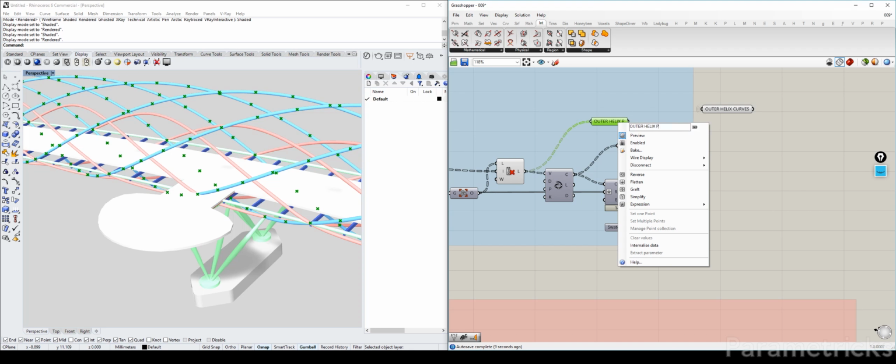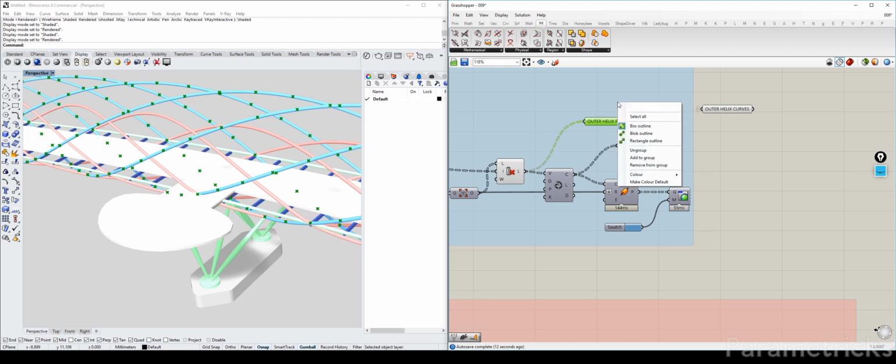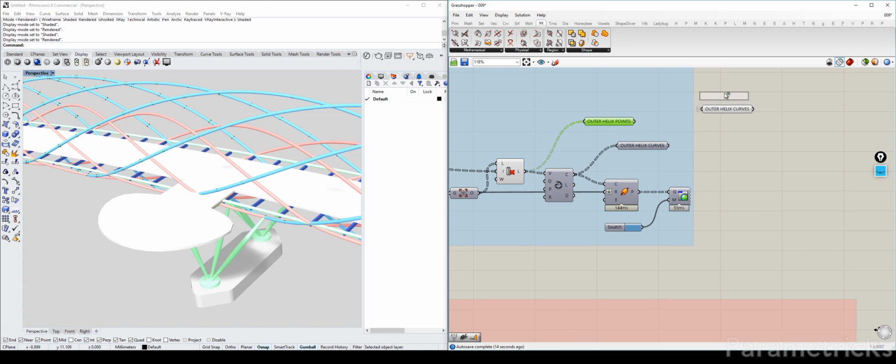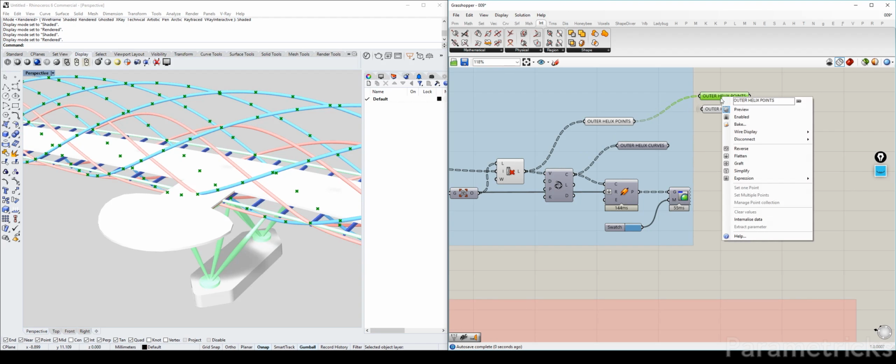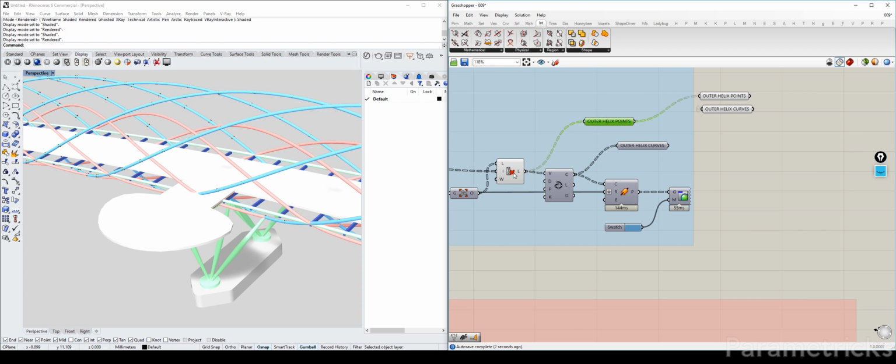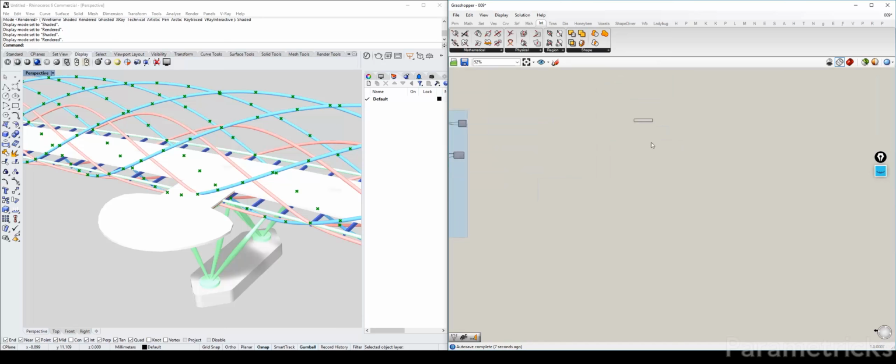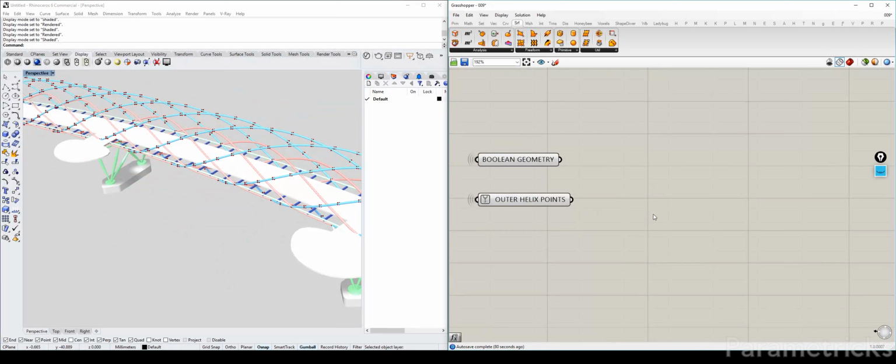But instead of curve, it's points. We are going to add that here and then make a sort of outlet for us to copy. Okay, I can copy that and paste it here. Alright, so now we have to make our Boolean operation, make a Boolean geometry into a geometry itself, because now it's just a curve. So we're going to do a boundary surface, make it into a surface, and then we can extrude it up